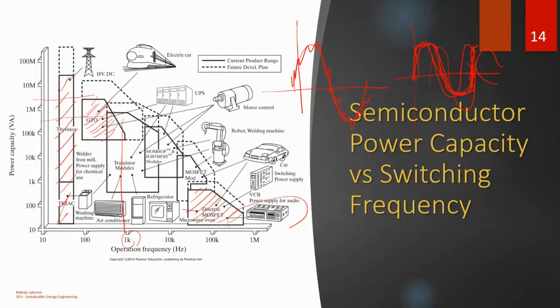So ideally in power electronics, we want the switching frequency to be as high as possible so that we could push the harmonics into the high frequency ranges so that we could filter them easily. So you get your 1% bonus, Karen.